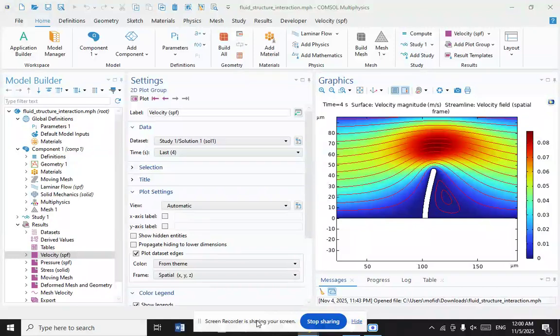If the interaction between the fluid and the structure is weak, only one fixed point iteration is required within each time step. These so-called staggered or loosely coupled methods don't enforce the equilibrium on the fluid structure interface within a time step, but they are suitable for the simulation of aeroelasticity with heavy and rather stiff structure. Several studies have analyzed the stability of partitioned algorithms for the simulation of fluid structure interaction.